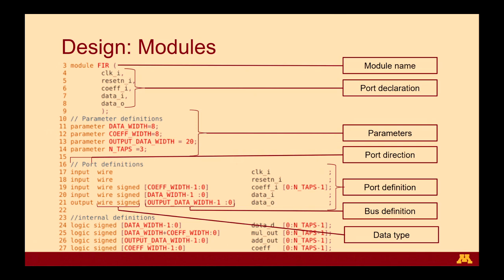If you have a system which has a very stringent requirement on the signal to quantization noise ratio, then you would want to experiment with these data widths to allow for lesser quantization noise in your design. So wherever possible, it is good practice to parameterize any part which you feel would change in later courses, or which you would need to modify to meet some design specification. In this particular case, the widths are parameterized, and even the number of taps are parameterized.